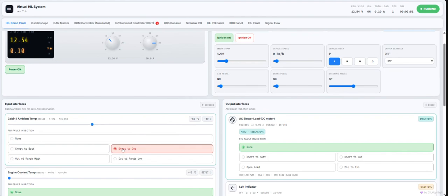If you want to do signal level analysis, in most cases on the HIL bench, we have to observe the value at digital level, so we have also tried to replicate the oscilloscope window. It is again a replica of the control desk, wherein you need to observe sometimes the values of some signals manually or graphically, for example, whether a switch button has been pressed or not. Those kinds of signals, if you want to try, you can just tap in here and observe it here.